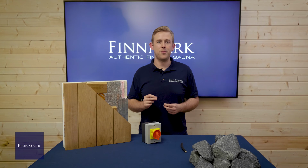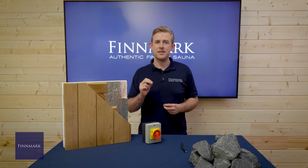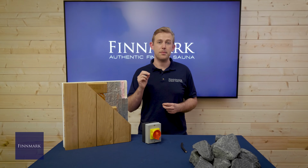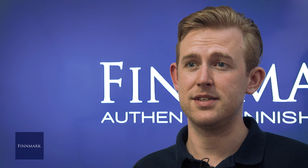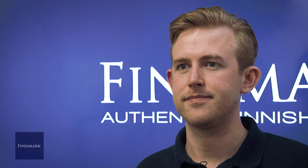With a full glass wall on one side, it very quickly strains the capability of most smaller sauna heaters. And looping back on what I said about power supplies, if you have a single phase supply, the maximum kilowattage of the heater that can be used is 9 kilowatts. It's therefore important to consider the size of any glazed apertures and the overall sauna size, as well as the limitations on the power supply when designing the sauna space.